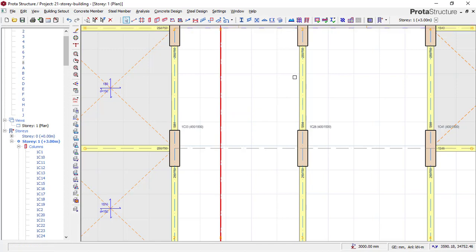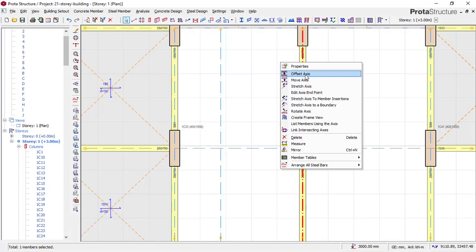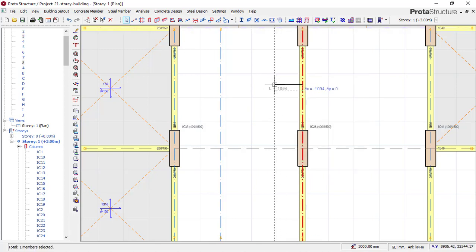Okay, the same thing happens to this area. Let's offset this area too. Offset. Now at this place, if you take the shift F2 key, you have to input a minus sign because it's going the other direction, 1,800, and I will click enter.